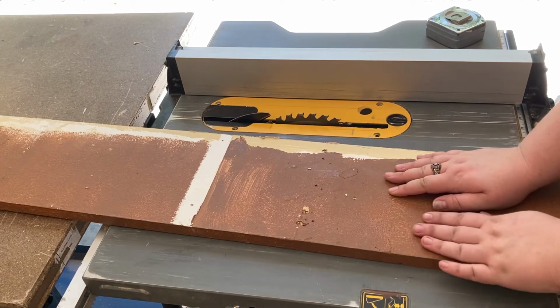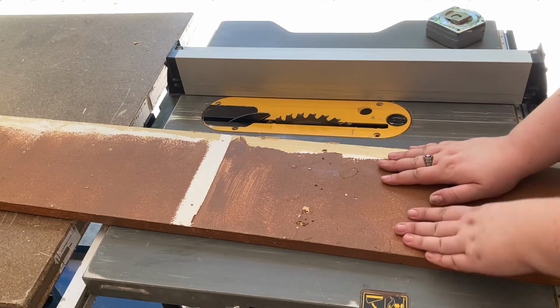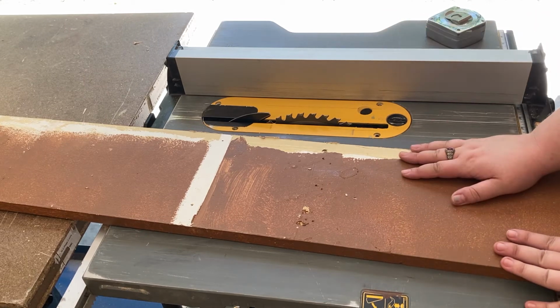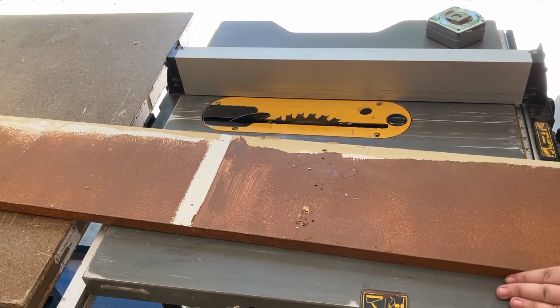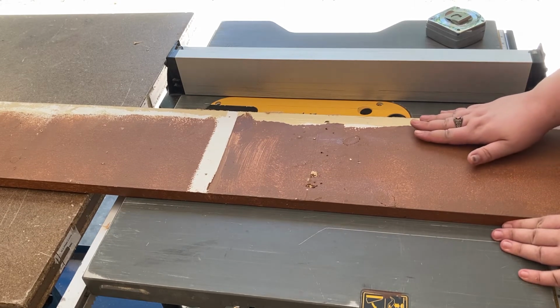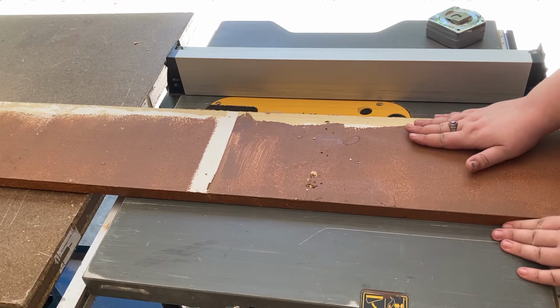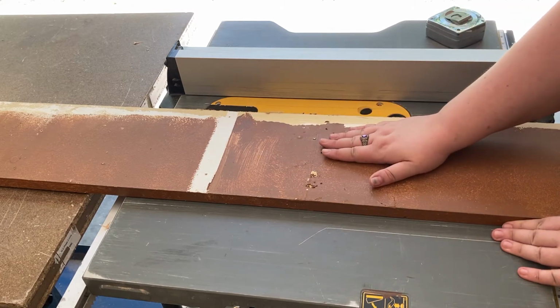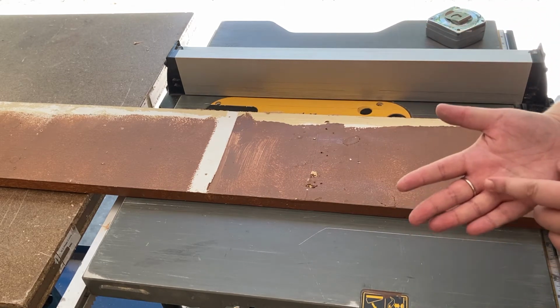It doesn't hurt anything to have it taller in terms of its cutting capacity, but it's not necessary, and you're only putting your fingers at greater danger. If you have it set so it's just barely cutting through the material like this, if for some reason, heaven forbid, my hand did go over the blade on top of the wood, yeah, it would still get cut up, but it wouldn't cut fingers off as easily.